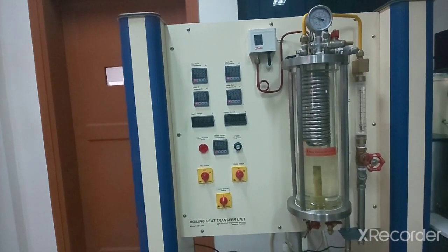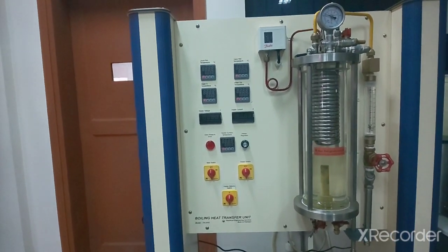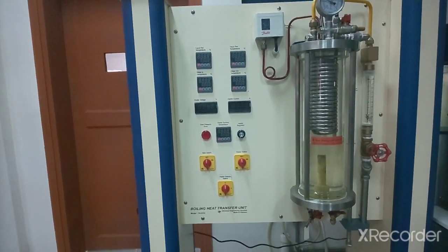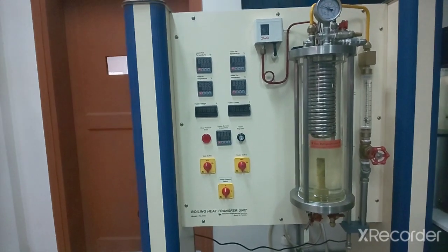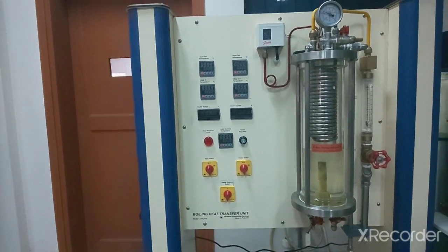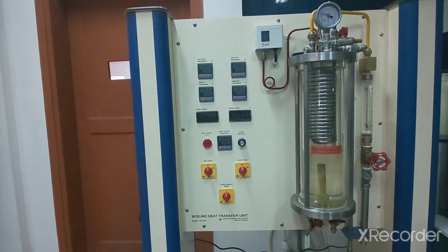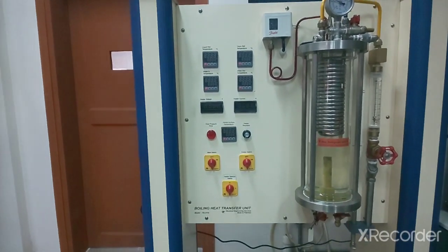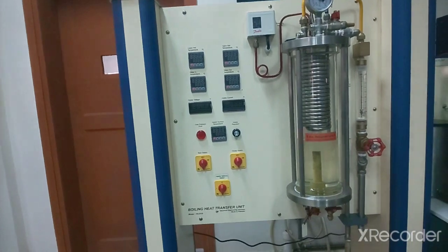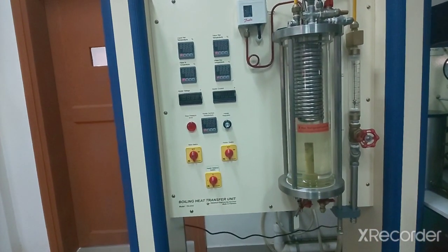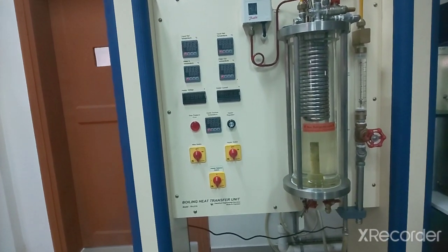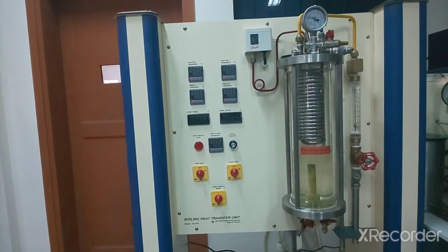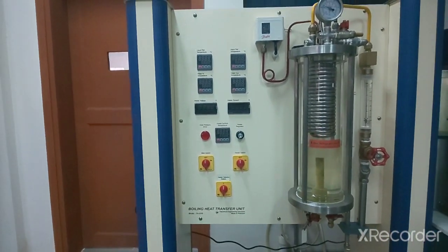In nucleate boiling, at the start the bubbles start to appear, and after some time those bubbles grow and start to leave the heating surface. They go into the liquid and pop in the liquid or at the surface, depending upon how far they have to travel and the temperature difference. Then continuous bubbles are produced, and that is complete nucleate boiling. Then there is transition boiling, and then the fourth type, which we will not be discussing here.